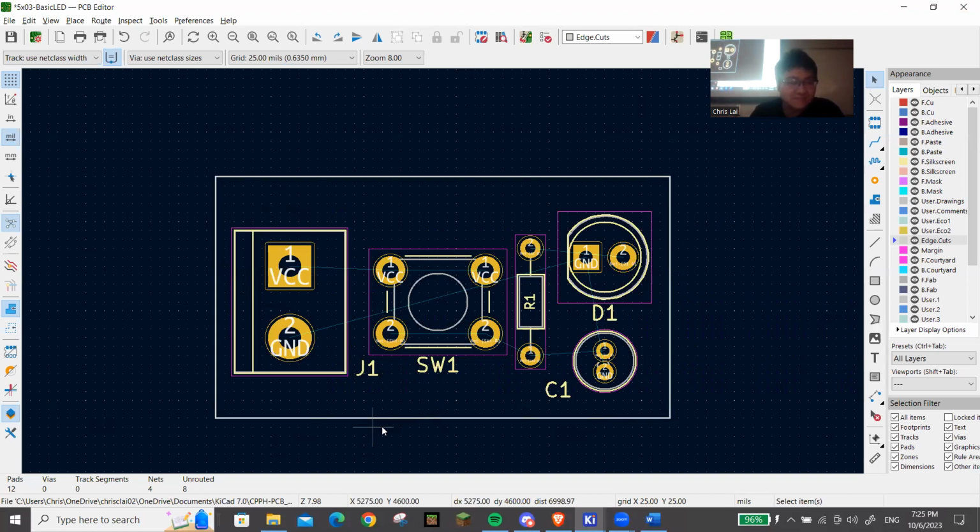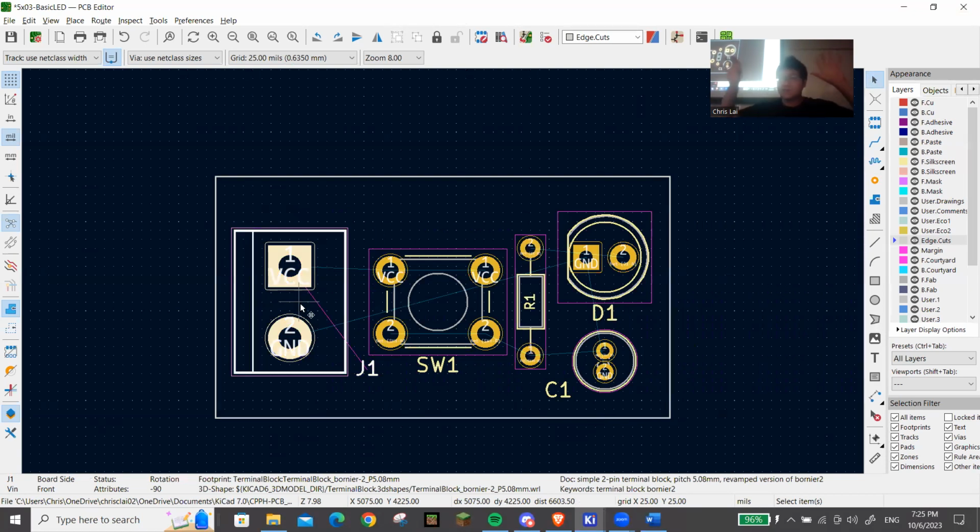I have questions. If I made a label invisible, how do I get it back again? Good question. You can probably get it back by deleting the item and then pressing F8 to update the PCB again. That spawns in the new elements because the schematic and the PCB are always linked together. So you would just respawn the thing back in.